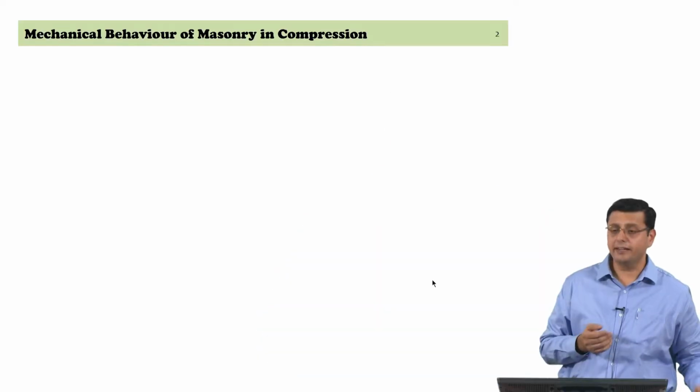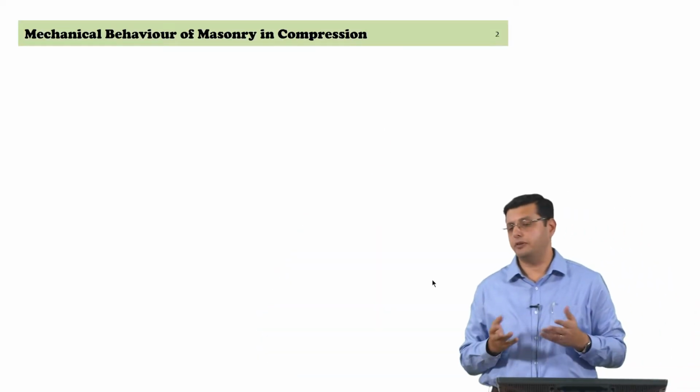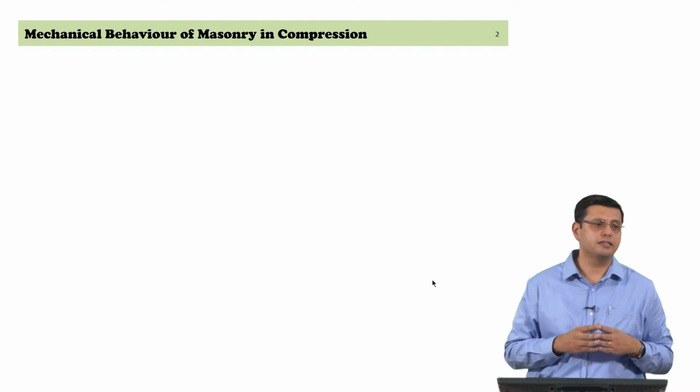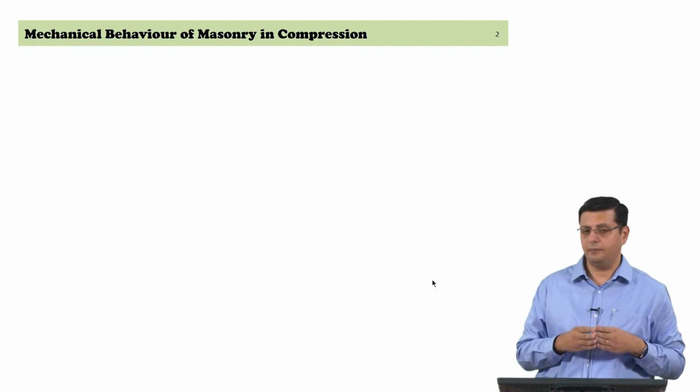This becomes the analytical basis for design, right. So the next module, which will deal with design, is going to be really feeding into the behavior of masonry under different actions. So I begin with the mechanical behavior, the mechanics of masonry in compression. This is something we have already seen quite carefully, particularly the coaction between the unit and the mortar.